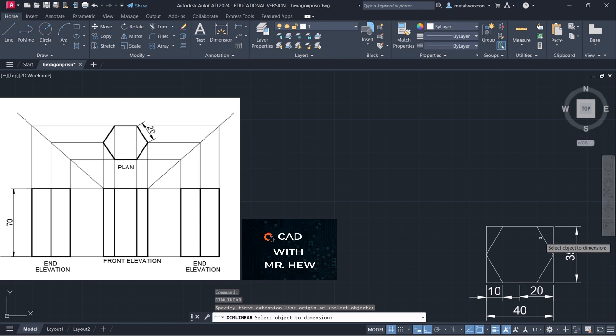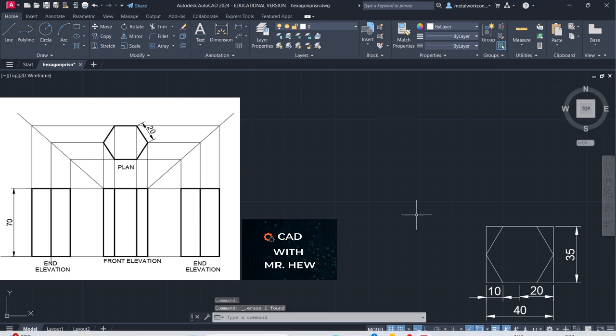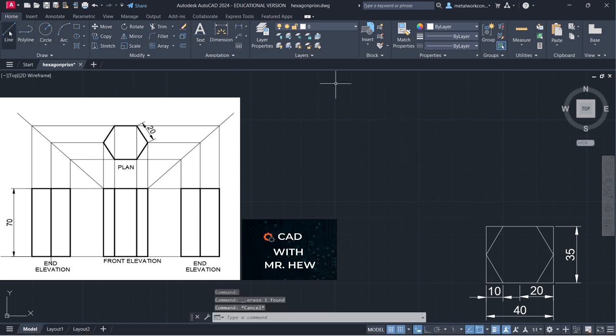All right. So the first thing we're going to draw is an isometric rectangle, and we're going to go line. All right, so we're going to draw this rectangle. We're going to select a point right here. So the length of this side would be 40 millimeters and the angle would be 30 degrees. Enter. All right, so we're going to draw this side now.